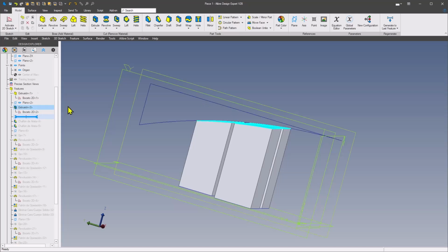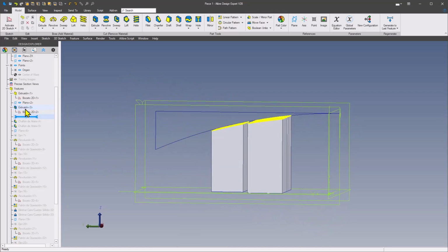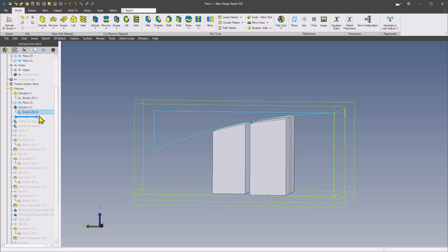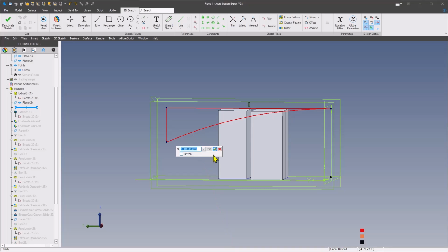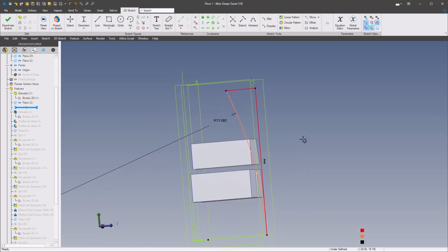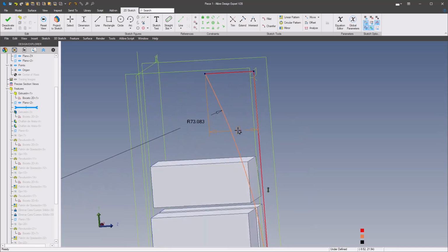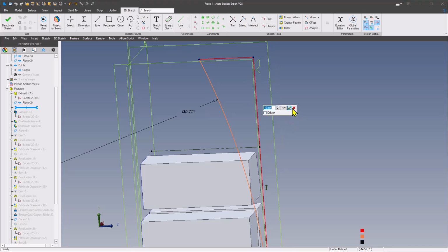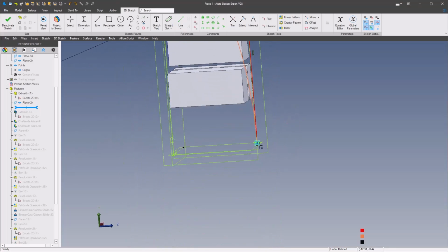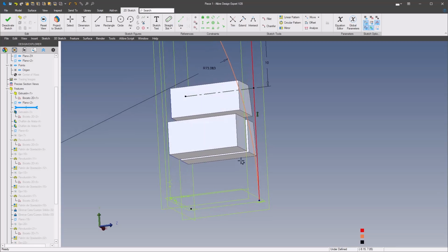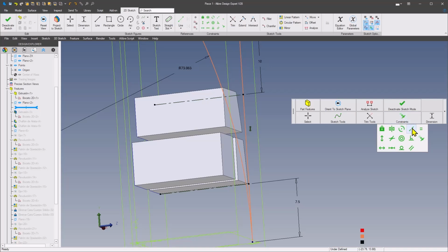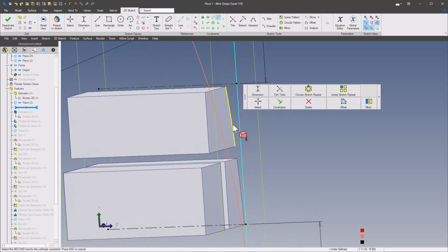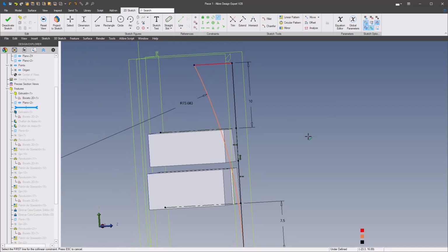So now the next thing is this monster here that you've got for this extrusion. So let's take a look here. And I'm going to just dimension this as it sits. And I'll leave that one out there. And then for this vertical line, we'll make that collinear there.